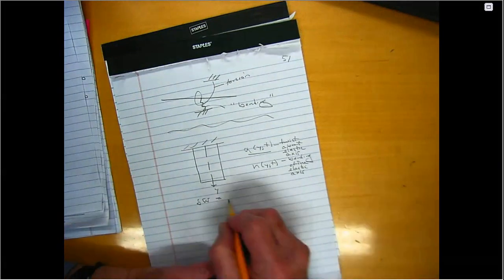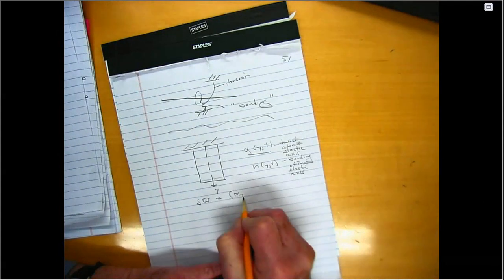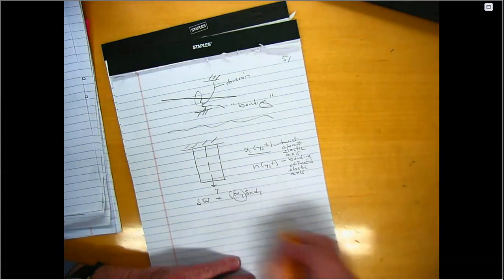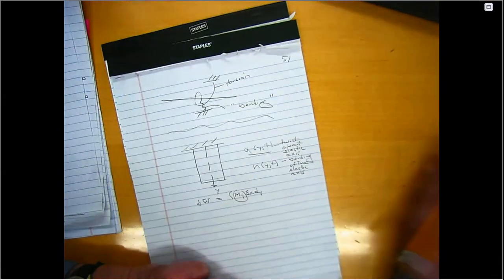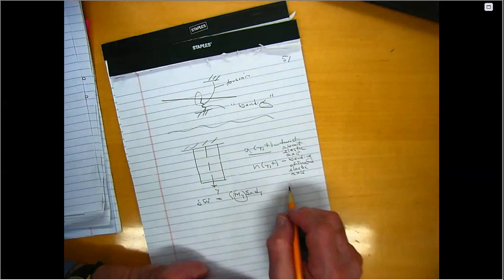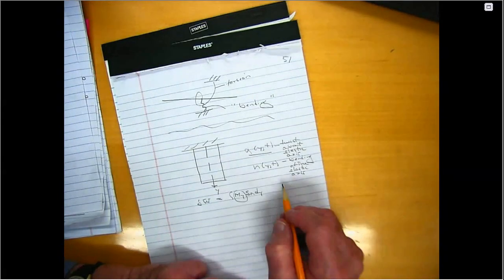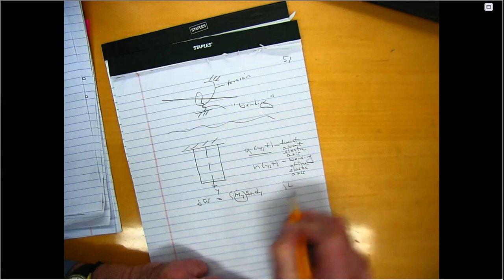Okay, so this is now going to be m sub y, delta alpha, dy, where this is the moment about the elastic axis per unit span. Right? But then, I also have some virtual work associated with the h deformation. And that's the integral of the lift, right?